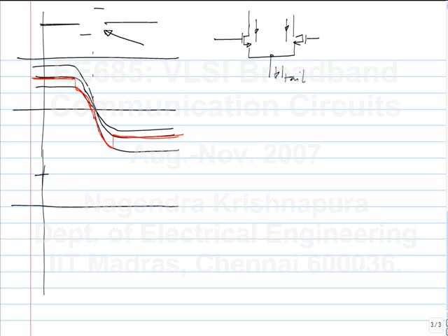So in reality, if this was the ideal output, what you see is that before the transition, you see less than what you should, and after the transition, you see more than what you should, and then you can have something of this sort. So it's not symmetrical on the positive and the negative side. Before the transition, when the tail current is reducing, you see less than what you would normally see, and after the transition, when the tail current goes beyond the steady state current, you see more than what you see. That's what you are seeing here.